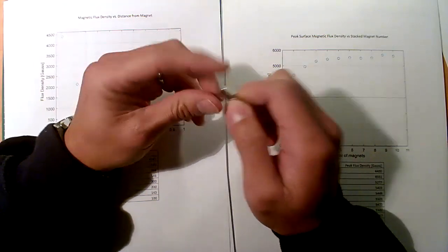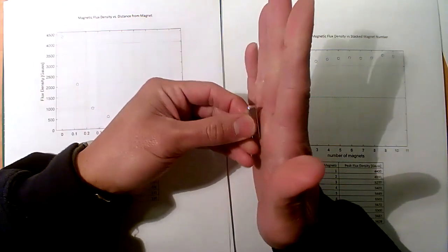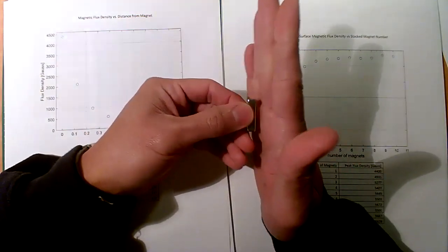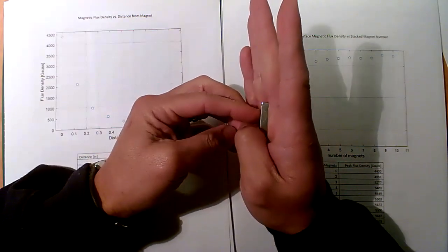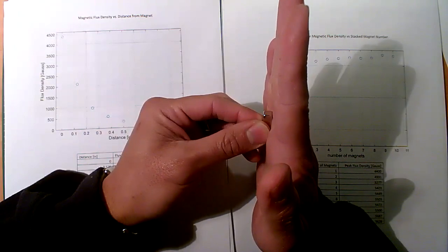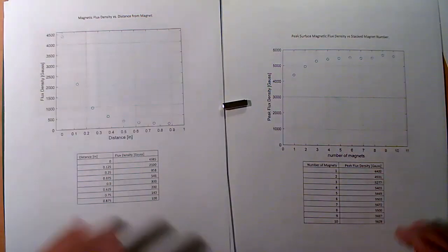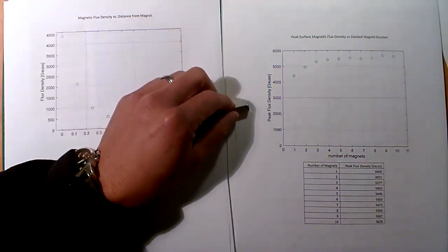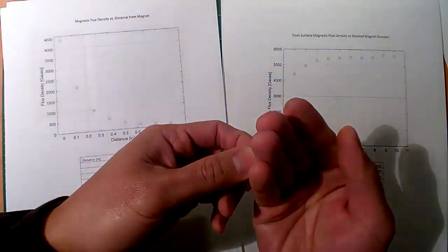Another thing you could do is if you have a piece of steel, you could stick it to the steel, because for steel, the magnetic field likes to be in the steel, something with high permeability. It'll get sucked to the plate, like a whiteboard with metal, so it has less chance of jumping away. But if you have this sitting in here and you get another magnet close, it'll literally jump out, right? And it can smash your fingers if you have a big magnet here, another magnet here, bang, okay?